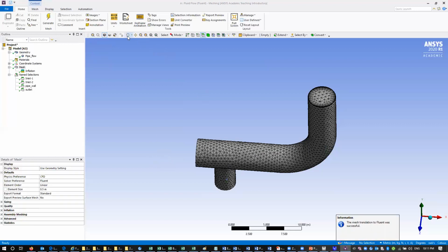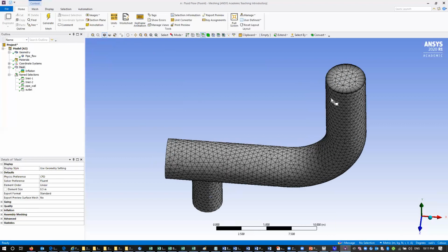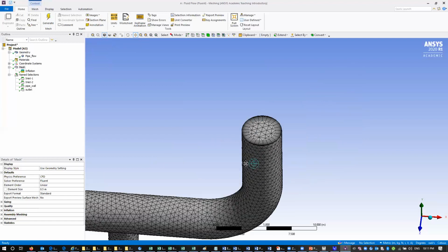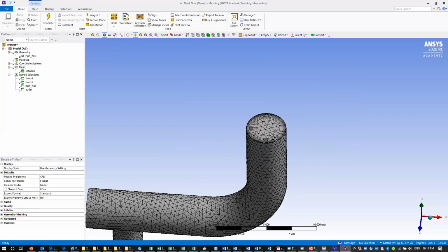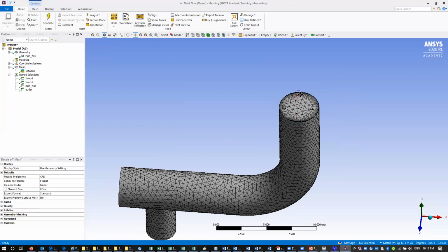You look at the new mesh. You have 10 layers. We call it a structured mesh near the boundary surface. So these 10 layers are for simulating the boundary layer flow accurately. Now, I finished the mesh.